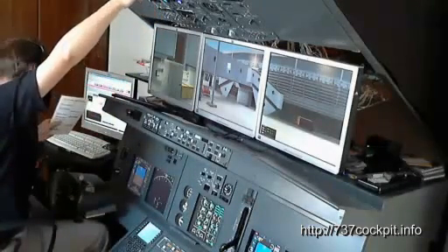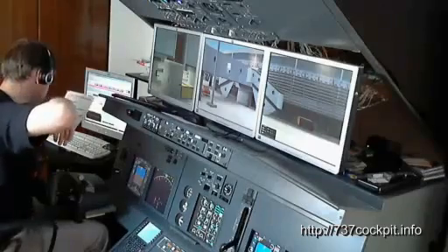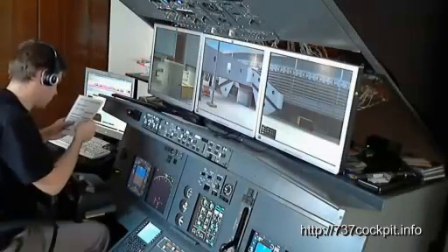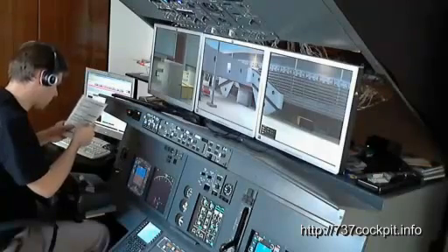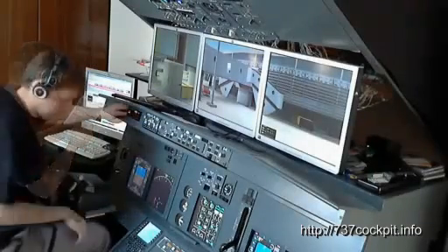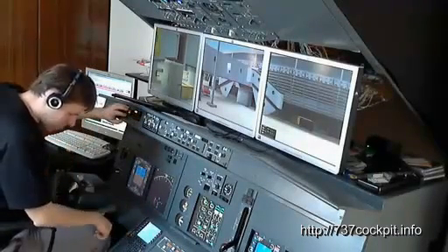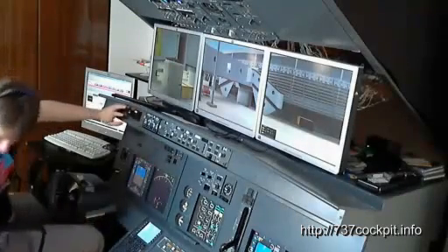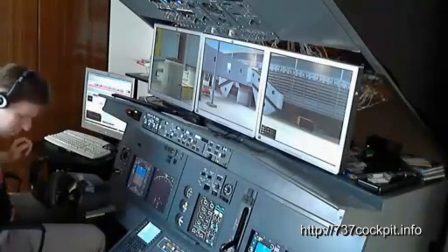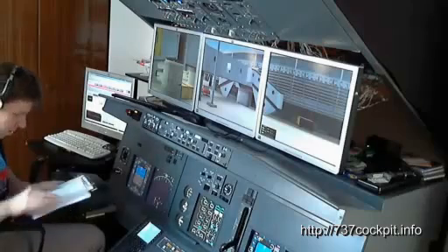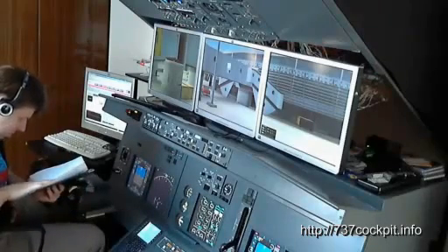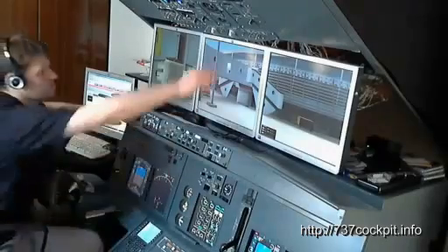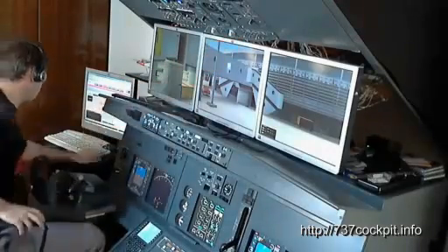Right engine cut off, left engine cut off. Right generator switches and left generator switches off. Parking brake set, APU power on. And we have a rest fuel of 2.3 tons. In our calculation we have 2.5 tons, so the doors can be opened now.